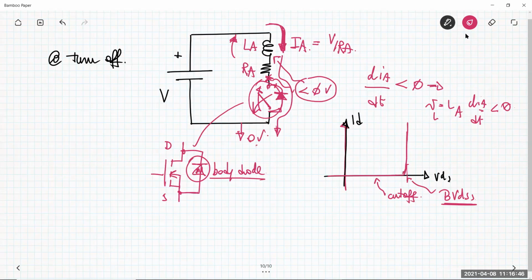And when it happens, the current flowing in these diodes makes these devices completely destroyed, because there is a very large value of current flowing here, and there is a voltage across the MOSFET. And so in that situation, the power dissipated during the breakdown operation is so high that the MOSFET is no more working as intended. Okay, permanent failures due to this behavior. So what happens here is that you open your switch because you want to turn off the phase, and the MOSFET blows up.